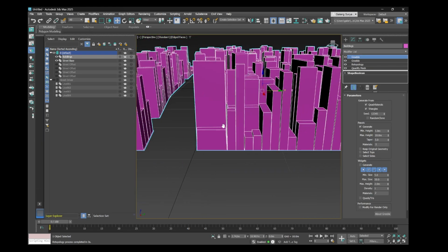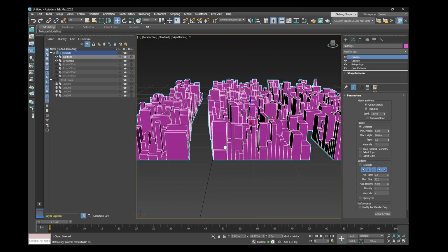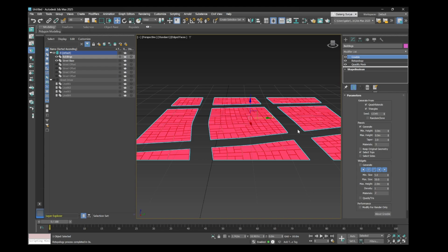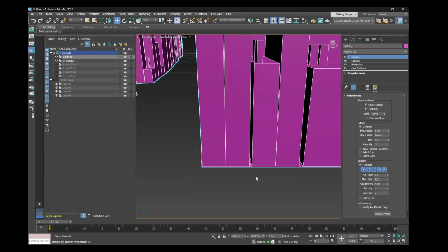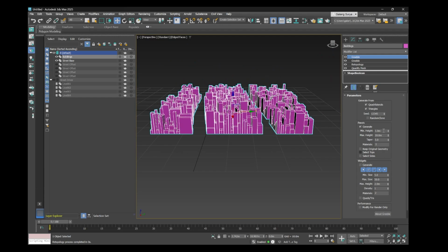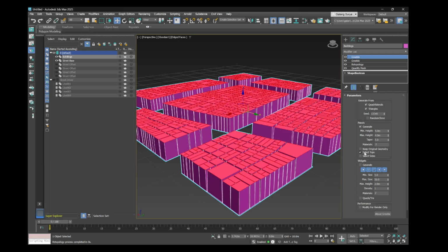Greeble is a fast way to generate building massing without manually modeling every block. With the Greeble modifier active, adjust the extrusion height and variation settings so different parcels rise to different heights, mimicking real-world urban form. Some buildings should be taller while others remain lower, giving a varied skyline. Try to keep it subtle at first to maintain a believable scale.